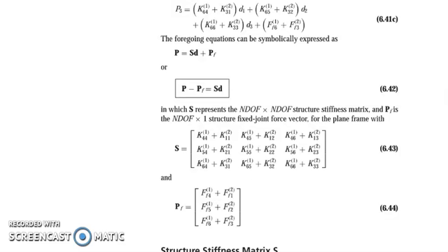Then you try to compare. Then you try to identify the number or the element on our member 1, member 2, or member 3. For example, if there are 3 members, that has a code number which corresponds to the column and the row. For example, you have 1 and 1, so you have to identify that one on each of the members until you finish filling up the elements on our matrix form. Then you simplify. You have now the value for our S, or the structure stiffness.